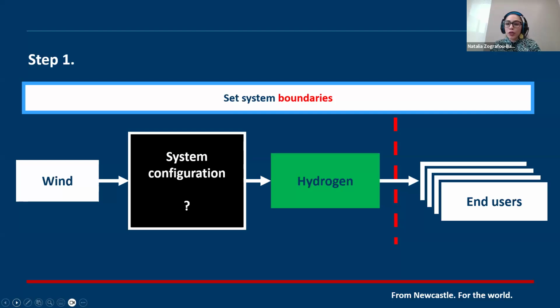And so this was important because in the beginning, for example, a natural thought could be, why are you not assessing resilience according to the hydrogen produced only? But in the case that we have a configuration where hydrogen is produced offshore, if something has happened, an extreme event that for some reason you can't use the pipeline, even though you can produce hydrogen, you cannot supply it, which is why we thought it was important to define the system boundaries.